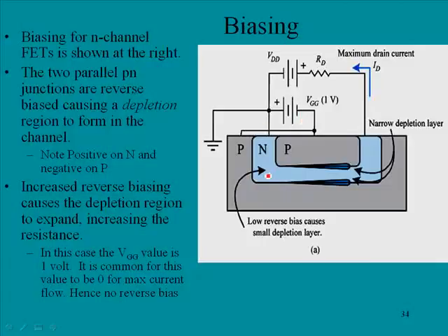Now this is just opposite the way that a bipolar transistor would work. If you had 0 volts on the base of a bipolar transistor, you would have no current flow. But with a FET, 0 volts on the equivalent gate would make for maximum flow of current.